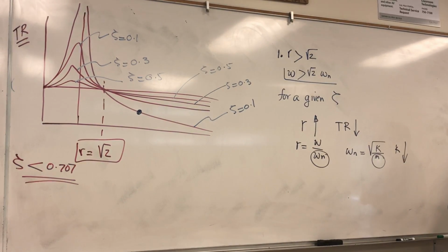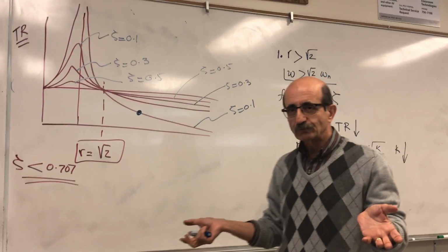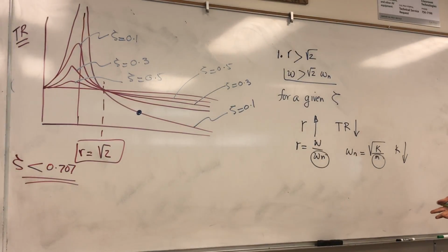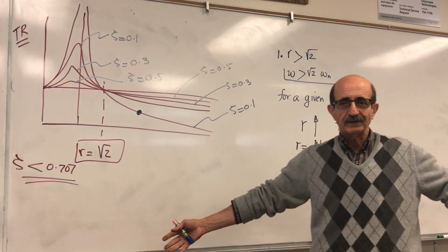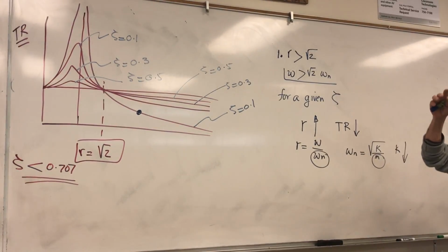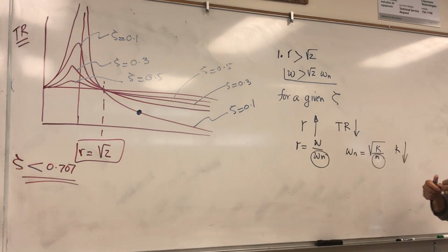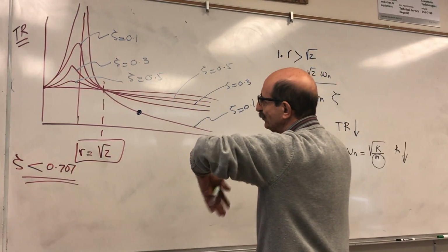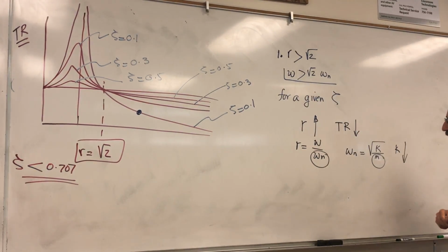If you make, for instance, the bumper of a car from chewing gum, right? It would be the most effective vibration isolator. But what happens? Smaller stiffness means larger displacement. So that's not good, right? Otherwise, you would put all these systems on a piece of string or something, very, very soft, right? So in other words, you have to make some kind of a compromise here.